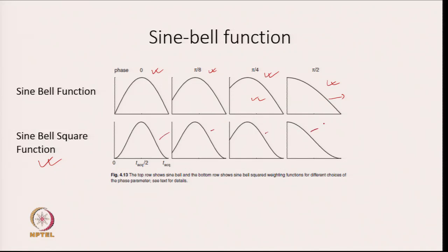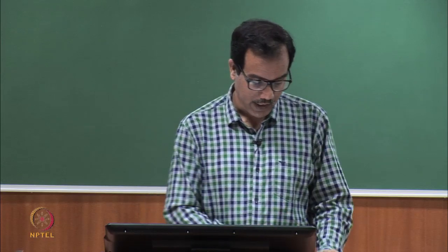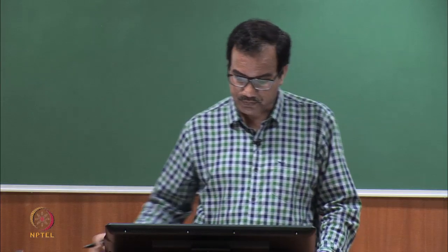So, I hope now you understand how to apply the window function. It is very important because it can affect your spectra. You can get better resolution, or you can get better signal to noise ratio.